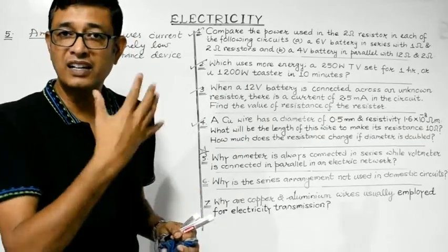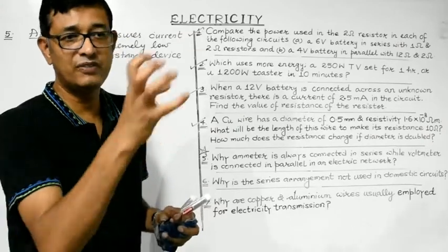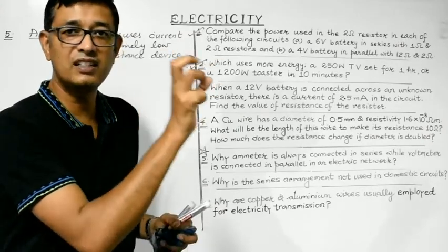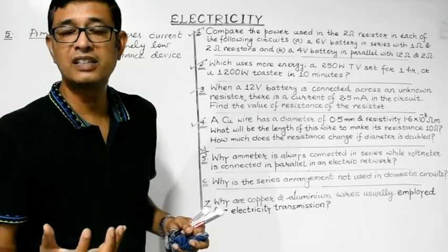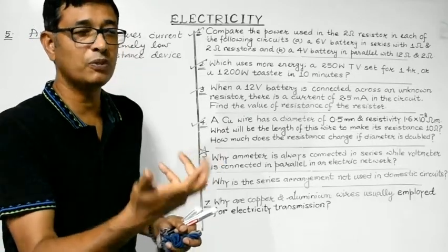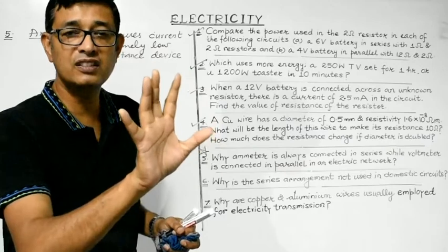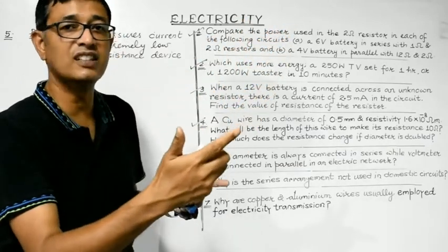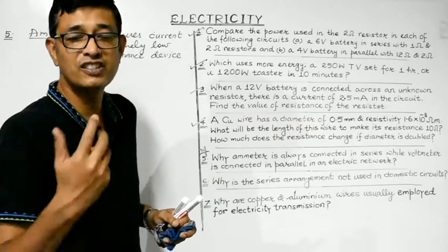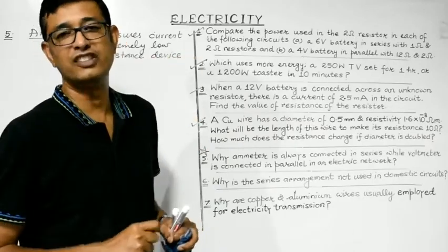If the main current remains unaltered, then the device will be able to measure the current accurately. Also, the voltmeter can measure potential difference, because if current remains unchanged, then V equals IR, the potential difference across any section of the conductor, will also remain unchanged, and hence the true value can be determined.